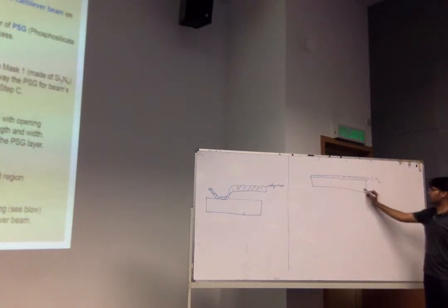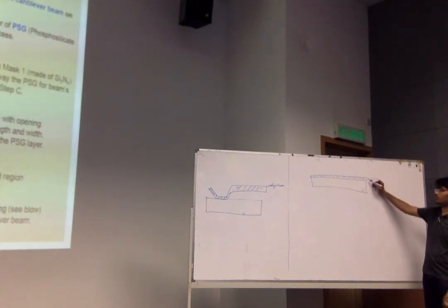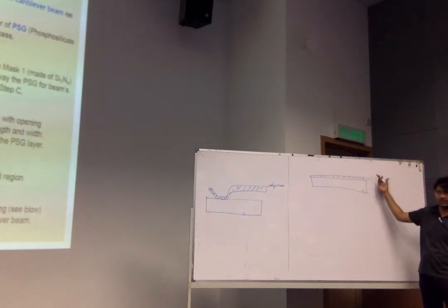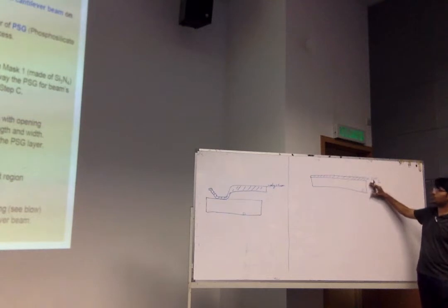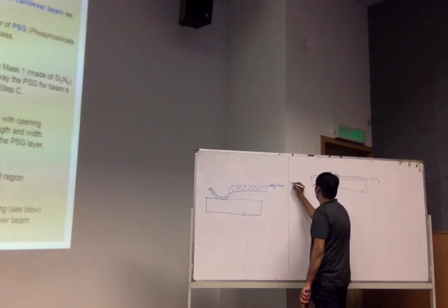So what they might have done, they take the silicon wafer, and then they send it inside the oxidation procedure. So what happened after a few minutes of time, the top layer of the silicon wafer becomes silicon dioxide. So now it is a combination of silicon and silicon dioxide. The next step they are trying to do, so the first step is oxidation.